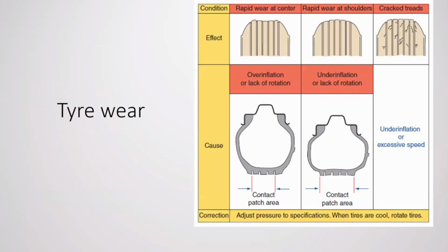Yes, the contact area will be increased, right? Contact area will be increased with the lower inflation pressure, so that the pressure applied on this particular area will be reduced. So then there will be less possibility of getting stuck inside the sand, correct?